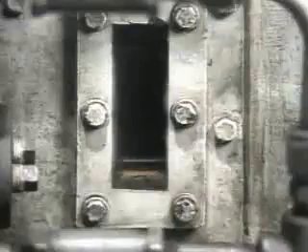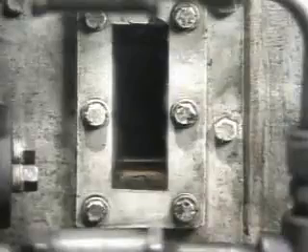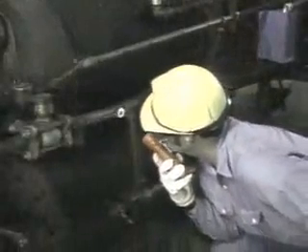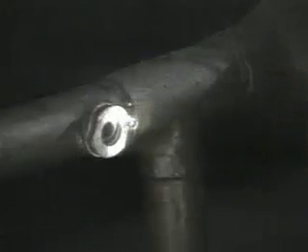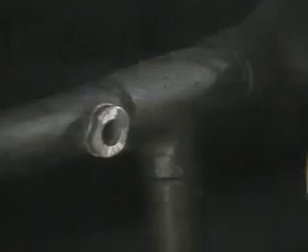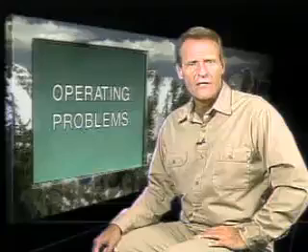The level indicator on the compressor's oil reservoir is checked to see if the compressor has enough oil for proper lubrication. If the oil level drops too low, bearings and other moving parts may be damaged. Now, there may be other indicators you should check to ensure that a system is operating properly. For example, sight glasses on the receiver outlet can be used to check the flow of refrigerant.